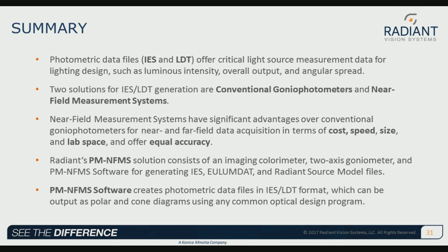Okay, great. So in summary, photometric data files, i.e. IES and LDT, offer critical light source measurement data for lighting design, such as the luminous intensity distribution, the overall output or total flux, and the angular spread of that light.